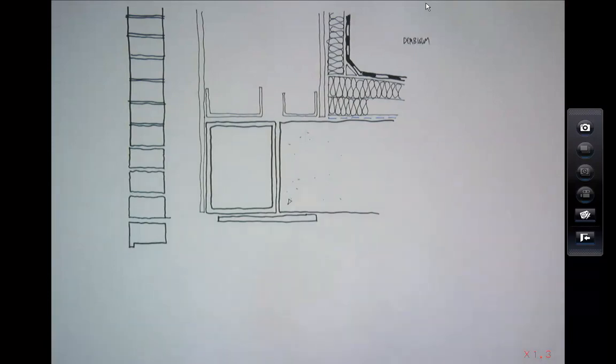So if you can, try and get a Derbigum, a hot melt flat roofing system. It will just make life easier for everybody. It costs a bit more, but they just don't leak. Is it hot when you put it on? The sheets go down cold like that, but they join it with a hot melt, and they put a thin hot melt layer down to stick it down. Yeah.